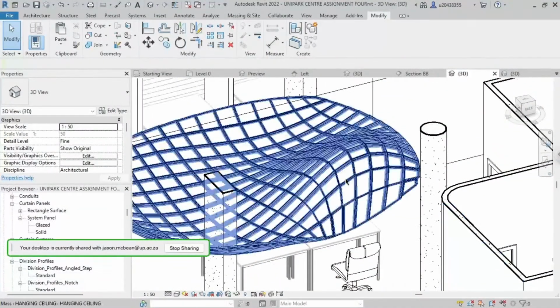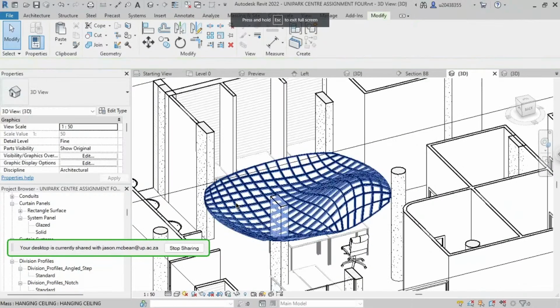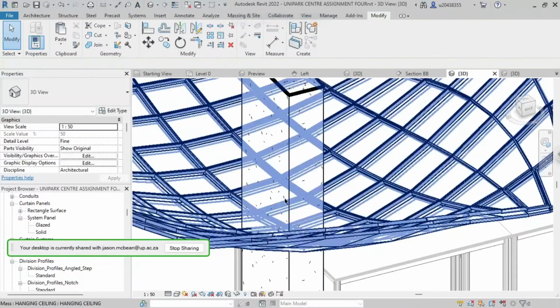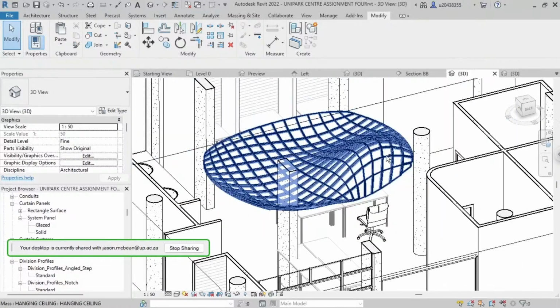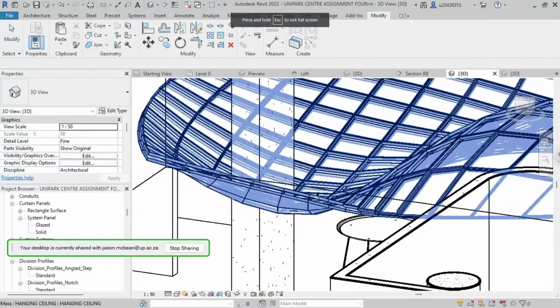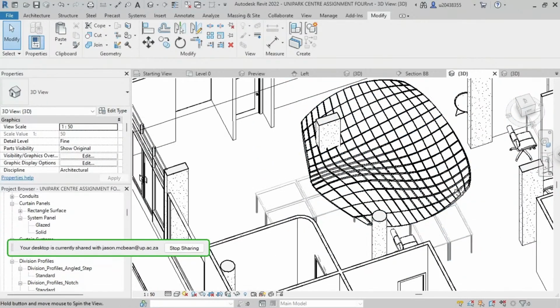You can then export this out and cut out pieces. This is tricky. You can export this to Formit now. Then in Formit, you can break away these pieces, cut away, and bring it back in. Leave it there as part of the column; you'll just have to find a way to separate that stuff from the column. But you can punch a hole in that face using an extrusion or a void extrusion. Cool, that actually works.